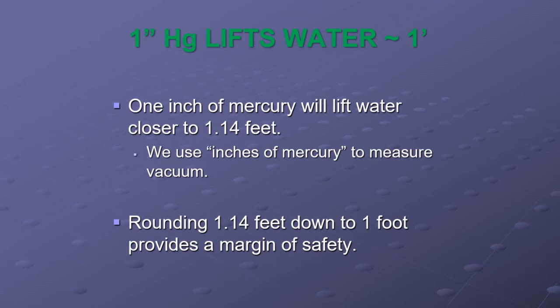Maybe my pump's not working at its maximum capacity anymore because it's old. Any of these things could happen. We round things so that we calculate our estimate. Are we precise? No, we're not precise. Are we accurate? Yes. 1 inch to 1 foot as far as vacuum goes and as far as lifting water goes, that's a perfectly good calculated estimate.